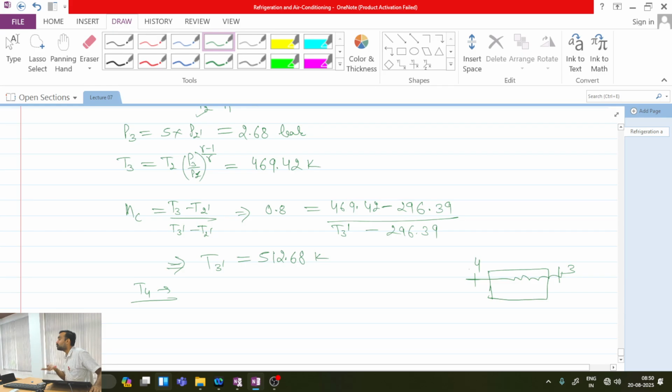But what is used for cooling it? For cooling it, the ram air is used, which is coming at temperature T2. Of course, whenever the ram air is taking heat, the other end of the ram air will be at slightly higher temperature than T2. So what is the lowest temperature of the cold stream available in the heat exchanger?